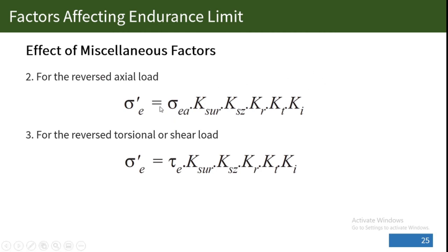We have the corresponding size factor and corresponding load correction factor, and in considering the three miscellaneous factors, we simply multiply the three factors into the expression. And also the same with the reverse torsional or shear load.